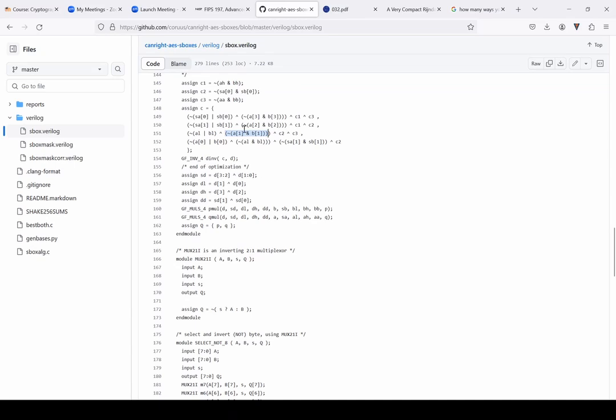But you see here in this implementation, he always used the NAND operation. Here is the AND, of course, he negated the output. And in this concept, you may tell the synthesizer that this is the NAND gate, but of course you can instantiate the NAND gate individually and force the synthesizer to just use the NAND gate. This is the way to implement this.